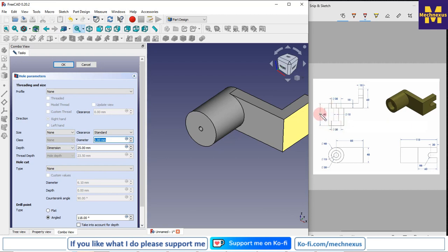If we do 70 minus 15 minus 40, so here our diameter will be 15 and depth would be 40 plus 15, 55. So this is the 55. While making the counter bore, first drill the minimum hole, the first hole which will be used to make the counter bore. So this is the 55.